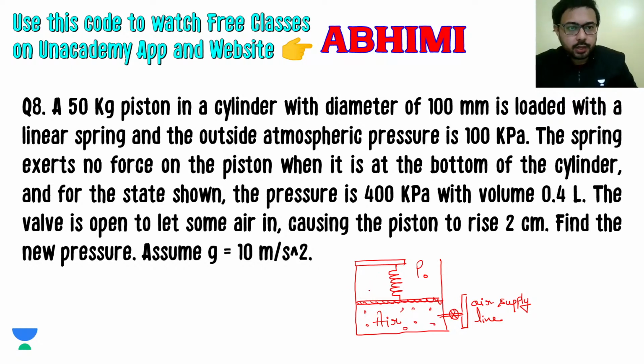It is also given that the mass of this piston is 50 kg, and the diameter is given, and the outside atmospheric pressure is 100 kilopascal. When the piston is at the bottom of the cylinder, there is no force exerted, so we can say the force due to the spring there will be 0 when it is at the bottom. But when it moves in the upward direction, there will be some force resisting its motion.